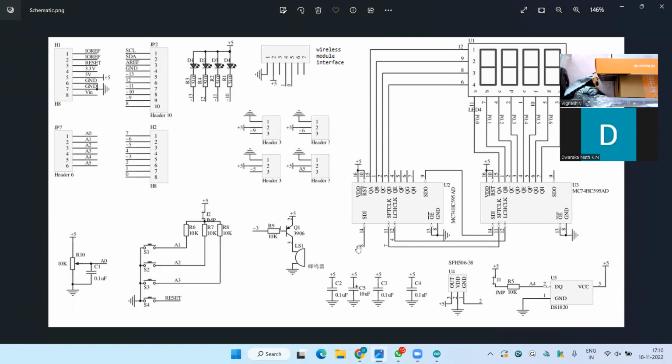Here we are going to give serial data input, and for output we have parallel output as well as serial output. For example, I'm giving the number 7 at the 14th pin. Here we have two clocks: one is the latch clock, another one is the shift register clock.